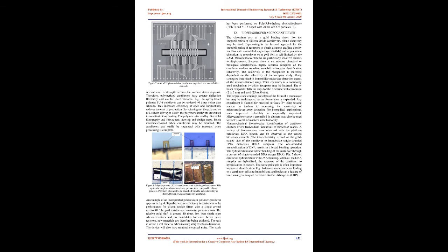Usually, two external resistors link the cantilever sensor in a Wheatstone bridge setup to the reference cantilever. It allows the feedback signal to be reached even where the deflection between the two cantilevers is equal, and thus noise is greatly minimized. Fig 2 displays a device for differential calculations of two microfabricated cantilevers. A small scale allows the vibrators to be resilient with a strong resonant frequency, which makes them less prone to external vibration.